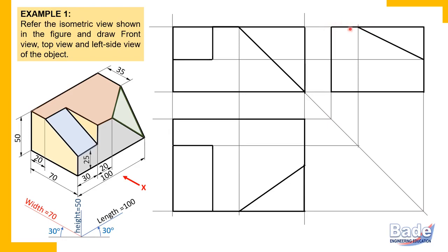Or you may measure 35 independently. Many students get confused how to measure this, where exactly to measure 35, in the sense, where to be measured exactly in the side view. So simple. Check here from the back end. This is back side. At top, that is at top, parallel to width. Width is in this orientation. So measure 35. Or you may project the 35 millimeter which we have already measured here by drawing projectors. So this corner is present here.